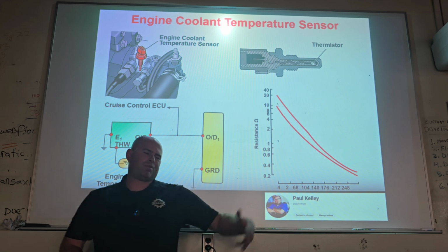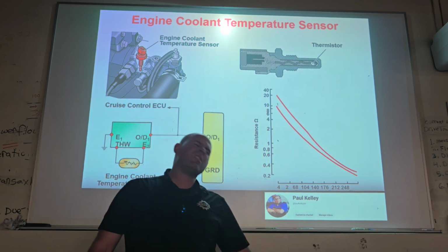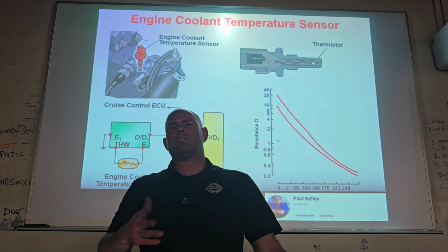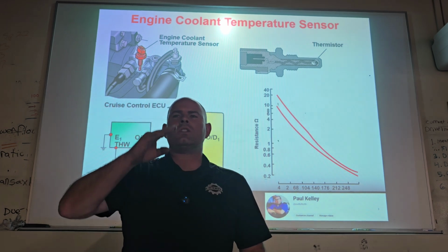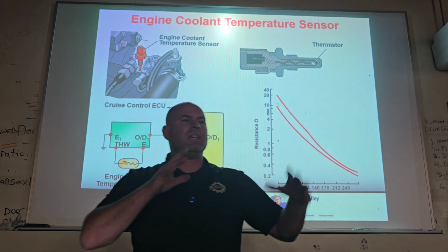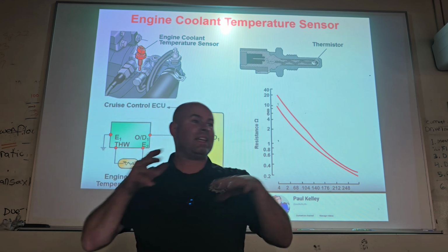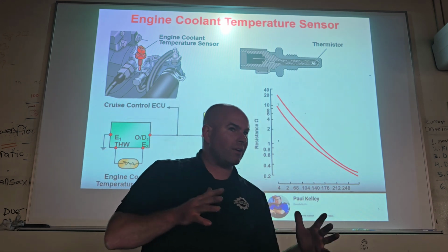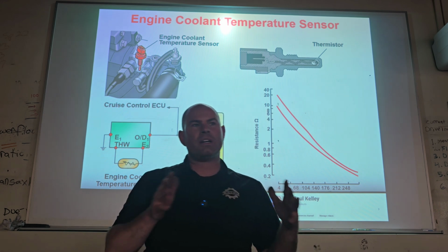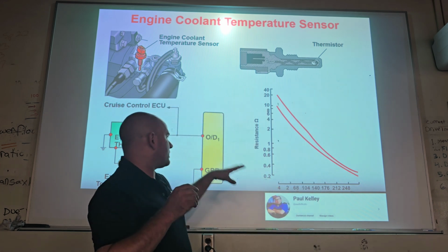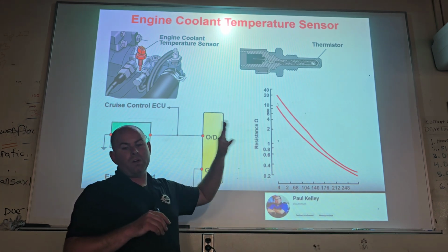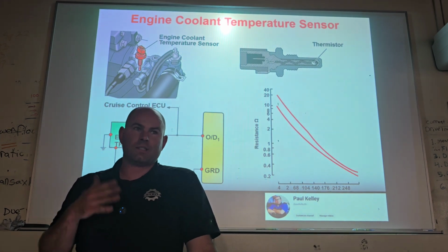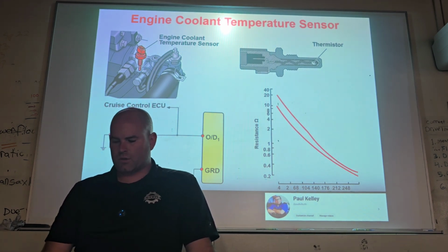And you're like, engine coolant temperature ain't got nothing to do with it. Are you sure? The reason that I would select that one is because an intermittent connection might go negative 40, 180, negative 40, 180. Does that sound like it's correlating with third, fourth, right? So just remember, some of this engine performance stuff will control how the transmission shifts. Remember the engine state of tune? This is kind of a continuation of the engine state of tune.